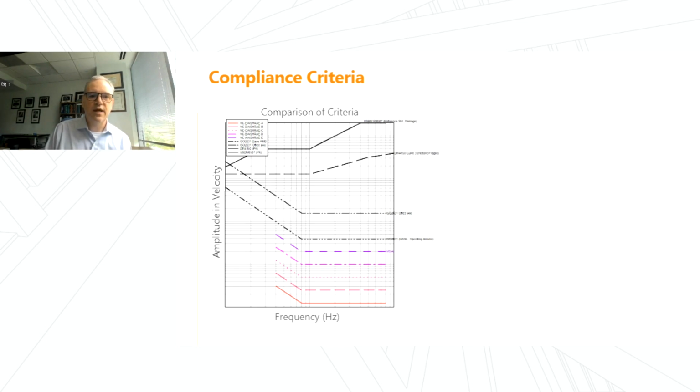So as a reminder, frequency matters a lot when it comes to consideration of vibration issues. Each of the lines below represents a threshold. If your building vibration is above the line, it could be noticeably problematic for that use. Below the line, acceptable. At the bottom, we've got somebody working on a lab bench. This represents a very sensitive environment: laboratories, clean rooms. The criteria are very strict. Even small vibrations can be disruptive to delicate equipment. More important, these vibrations are imperceptible to humans, so we can't use our own context to judge them.